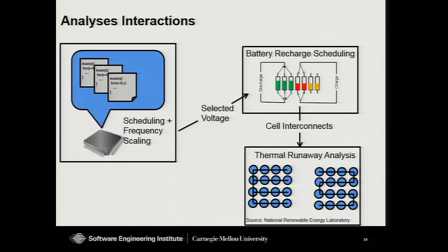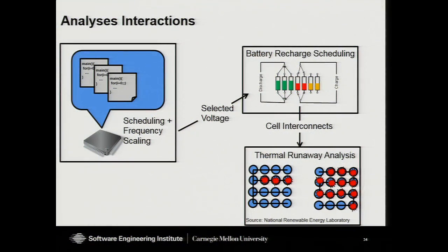Think about a hybrid car, right? And the benefit of having this connection between cells is that you can reach the appropriate voltage by connection, right? So you connect them instead of doing an analog adjustment of the voltage, which is more efficient. Which is very good, but the problem is the next one, right? It means that, of course, we have these batteries that overheat. If we change the connections between the cells, then we have different properties of thermal dissipation. And if we have different thermal dissipation, then we can run into problems such as the things that happen with Tesla and the Boeing 787, right?